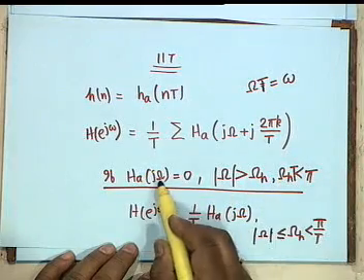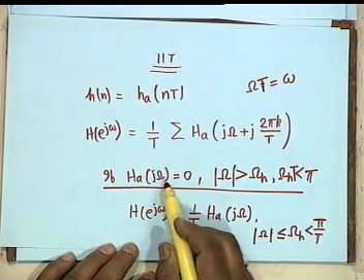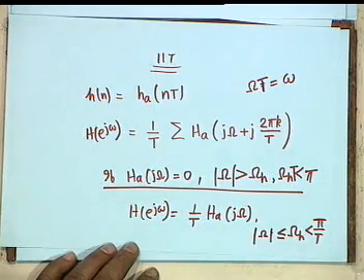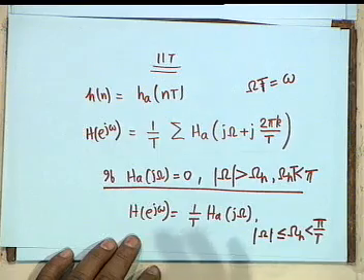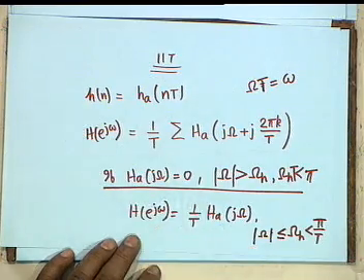It's very simple. Small omega is capital omega multiplied by t. If the analog transfer function is band limited, then our impulse invariant transformation will work beautifully without any problem.